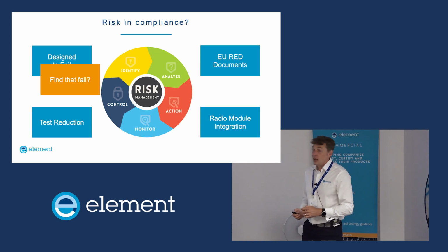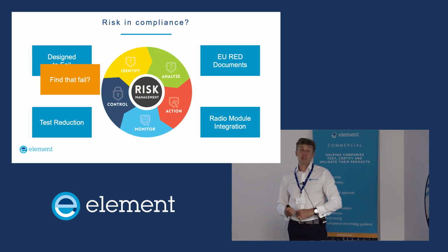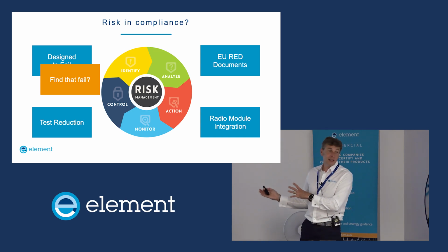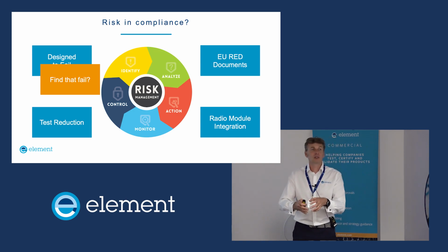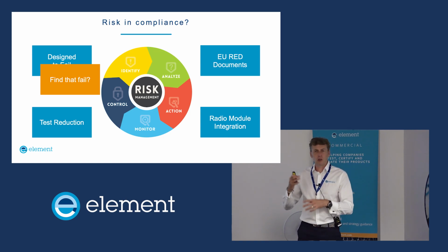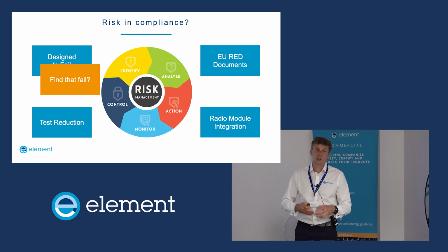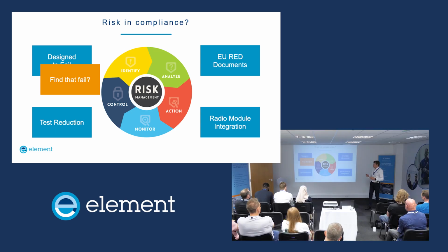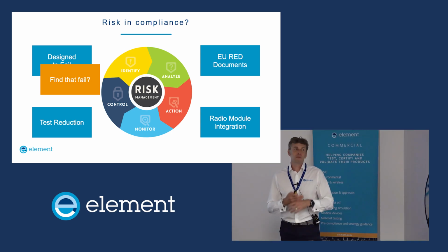And the classic case of where most people take the most risks is if they take an approved radio module and they install it into something else, and they say, I'm going to do some spot checks, but I'm not going to fully retest everything, because that looks like a lot of work to fully retest a radio module. So that's a massive source of risk for anybody doing that. And we'll come on to that in a minute. But if there is a failure somewhere designed in your product, you could look like you've passed all the tests by testing 1 or 2 modes, and then you're selling your product. But how do you know if your customers all find that failing mode, your product's going to get awful reviews, maybe bad press?